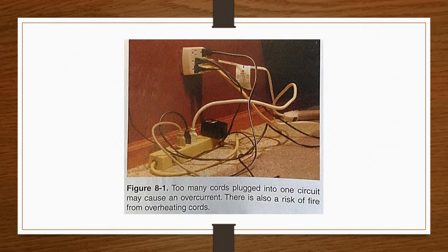Causes of overcurrent. The overcurrent may be a result of overload, short circuit, or ground fault. Any of these conditions, if left unchecked, could cause a conductor to heat up enough to degrade the insulation. This damaged insulation may expose the conductor to other conductors, metallic boxes or conduit, or people.